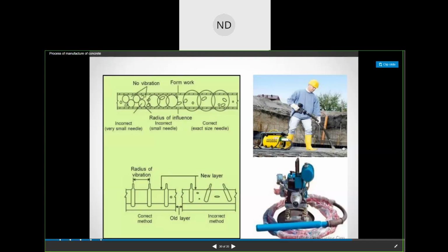You need to prepare the concrete slab. So obviously you need your concrete to get placed properly and move inside the reinforcements properly without any air being entrapped. So after placing the concrete we put this vibrator inside so that there is vibration, and any gaps present in the concrete will be removed and the concrete will settle again.